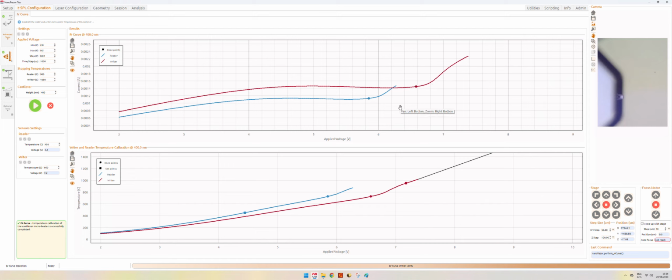If we didn't place the cantilever holder correctly to the machine, then we will not see a good electrical response because the electrical connection is not good. These are fundamental information that we need to know when starting using the NanoFrazor, and in general we can also get other useful information like which voltage we need to apply to reach a certain temperature.